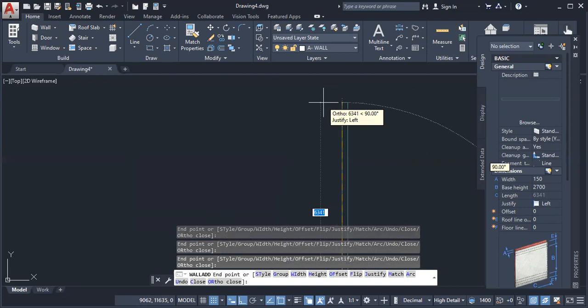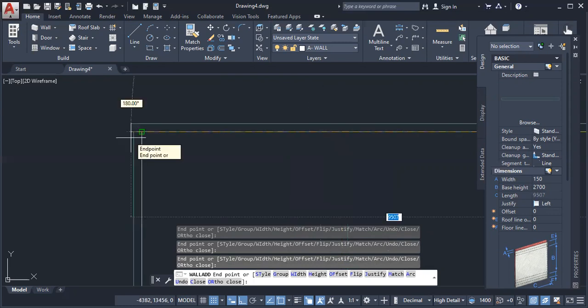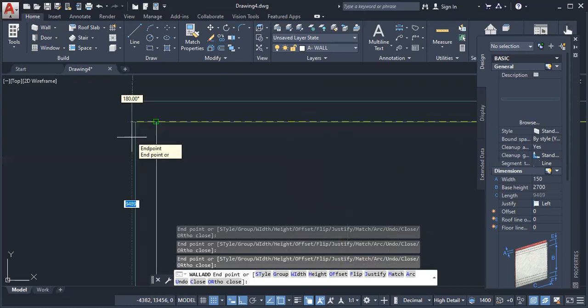All right. Something else that you need to be mindful of is that box that pops up. When you're drawing, I would like you to take special note of where that green box pops up. If this is right justification, that box will pop up at the right hand side. If it's center justification, this little box right here will appear at the center. If it is left justification, it will appear to the left of that line.